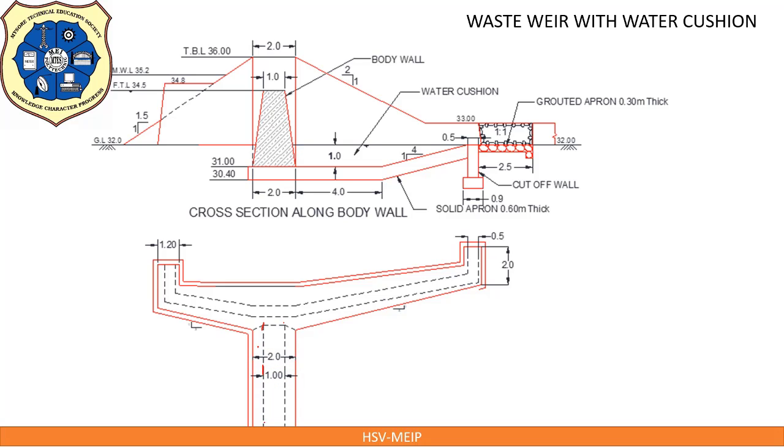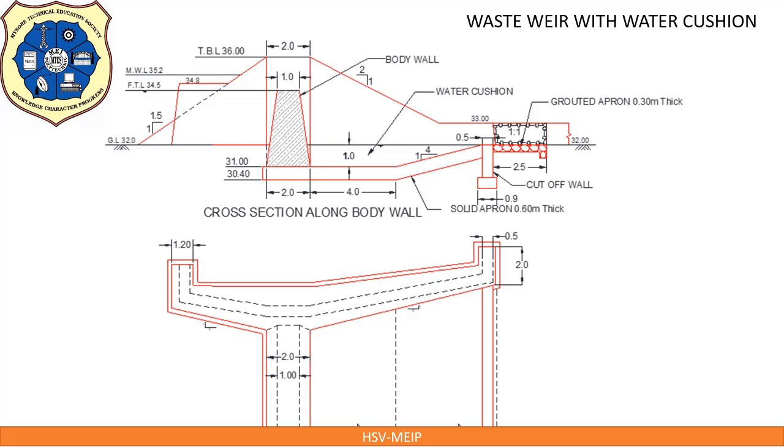Whatever details are not visible should be shown by hidden lines. Mark solid apron lines and cut-off wall lines along with concrete offset. This solid apron and then this concrete projection line. This completes the half plan bottom. Hatching can be done after completing half plan bottom.